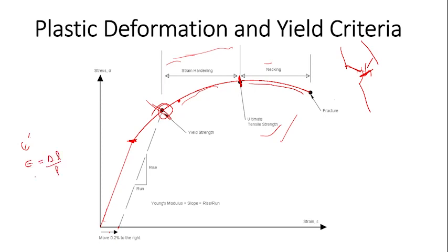So till here, if they are asking elastic recovery, and if they mention true strain, then you have to take true strain. If they didn't mention anything, you take engineering strain, right? You always have to take the initial length only. Both are the same. They will not ask you to calculate elastic recovery as such, it's just the strain, the elastic strain.